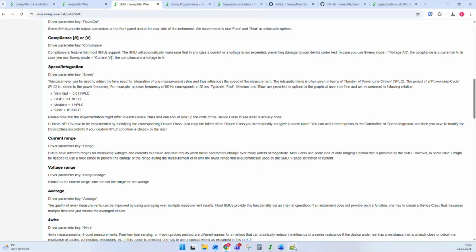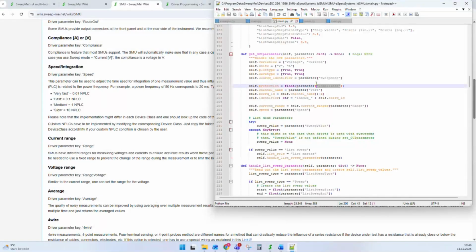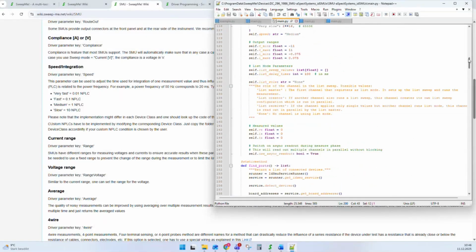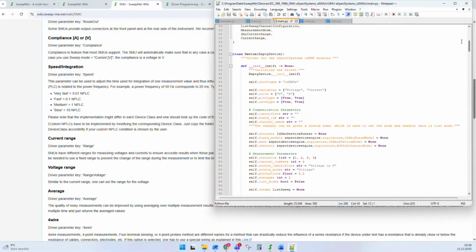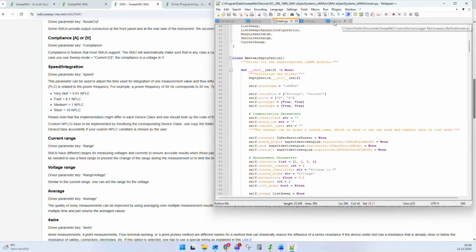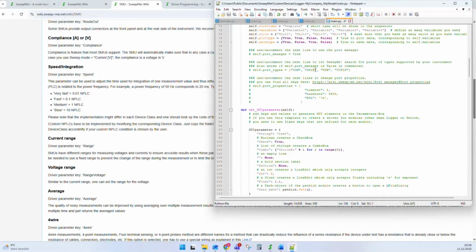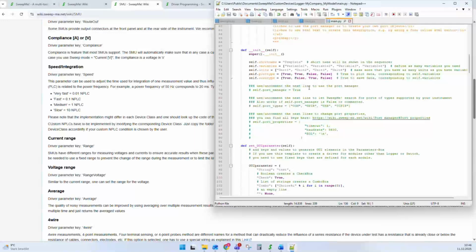Let's go to the port management. Port management means that you have to interface with these instruments and you have to send commands. And there are some kind of standard options to make this easier. A lot of instruments are running with either a COM port, a GPIB, USB TMC, or TCP/IP.